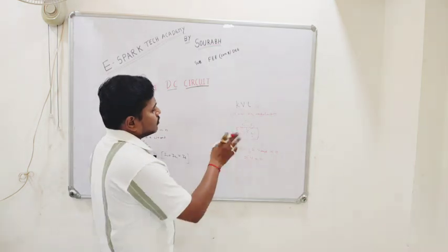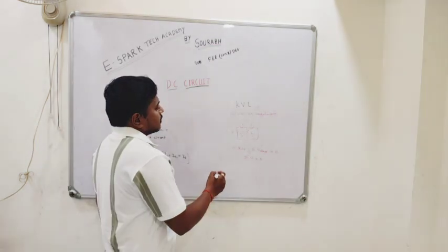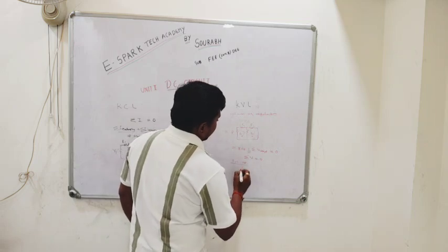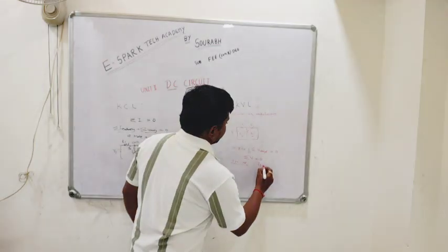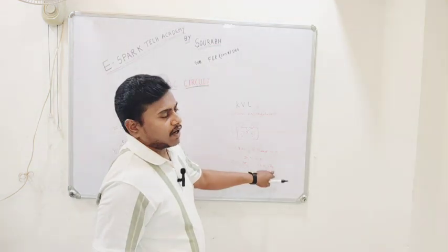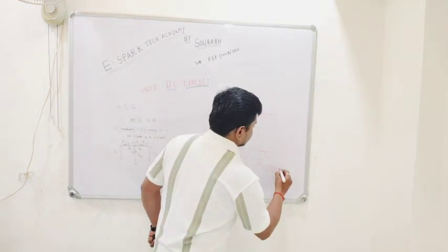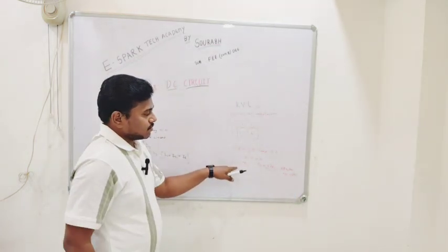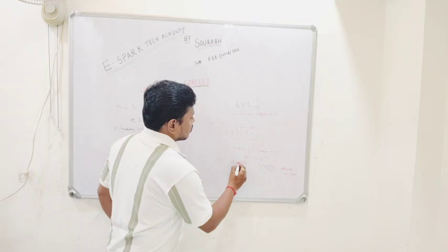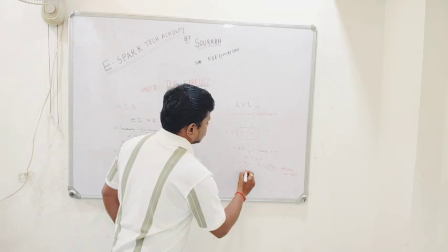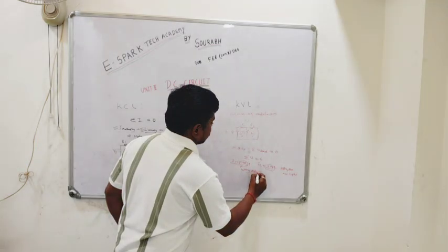But when you go through solving this kind of questions, you will be getting some answers in negative. Means if you get I1 as negative and I2 as positive, the positive answer indicates that your assumptions were correct. And here, if your assumption goes wrong, the negative current in amperes will be the answer for wrong assumptions.